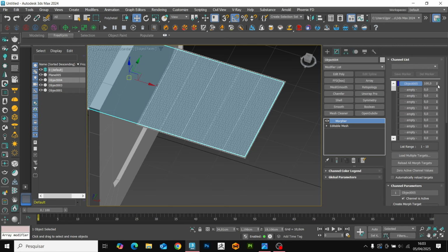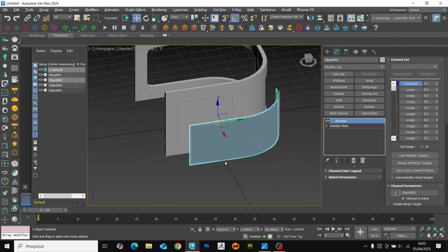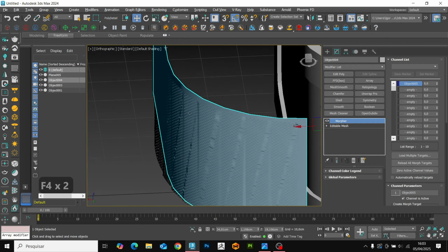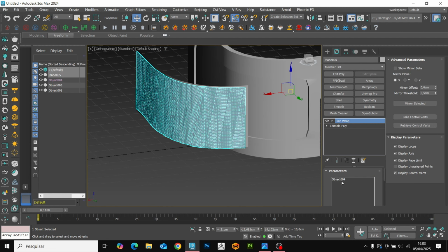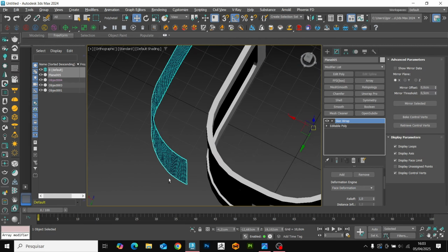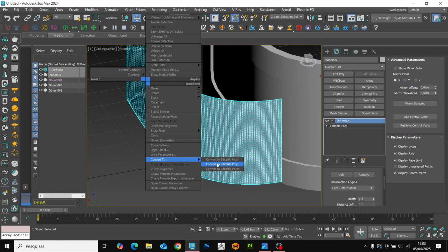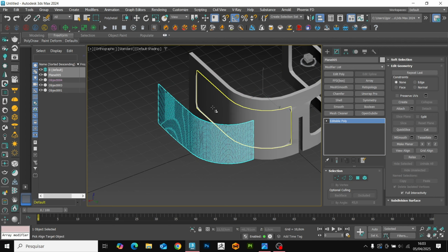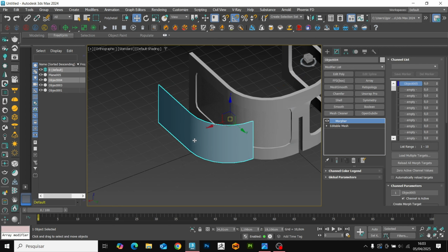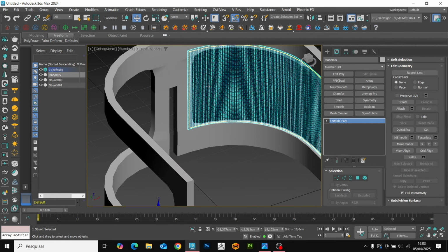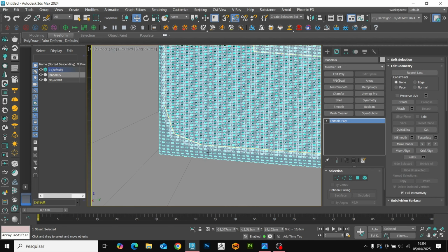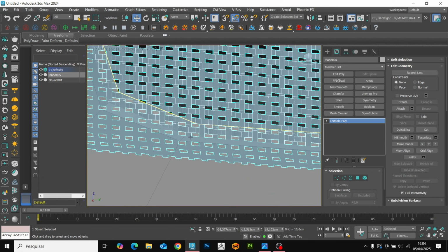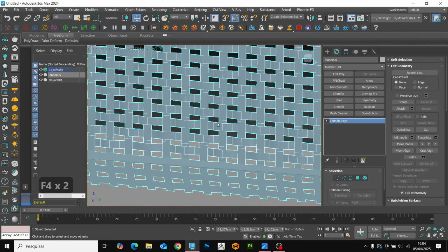Now, we return to our face that we created with UV mesh. And here, we lower the value from 100 to 0, so it returns to the original position. You can notice that it's not working correctly. Let's adjust this by changing our skin wrap deformation to face, and then we have our detail working correctly. I will convert it to editable poly, and now align it to our face that was created first. We can delete this copy and delete it also in the face. Here we have our detail working correctly within our structure that we created.